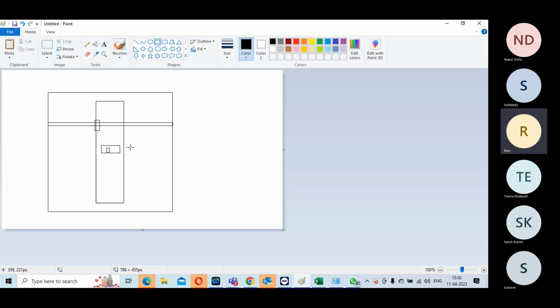But these rails will be M1 only, right? M1 only. This one will not sit because this won't connect, because there won't be an M1 pin over here for this to tap like this. This will be double height again. You have to understand, this whole technique is very important. So the legalization is, this one won't have VDD because it's not supposed to, because this one would have got hooked to your secondary power line.